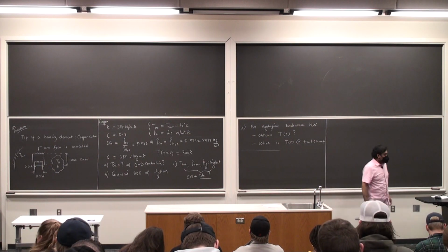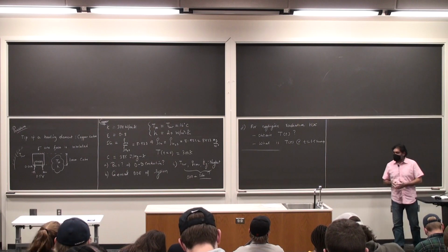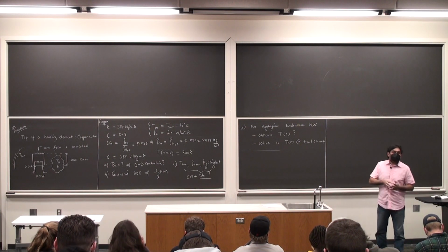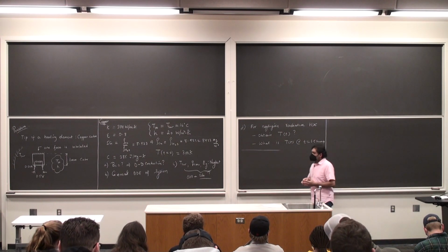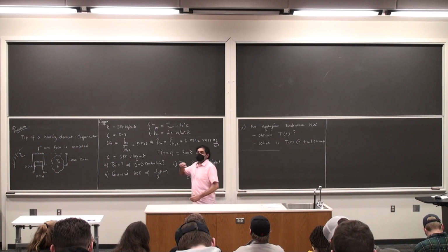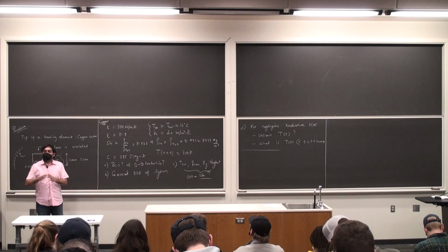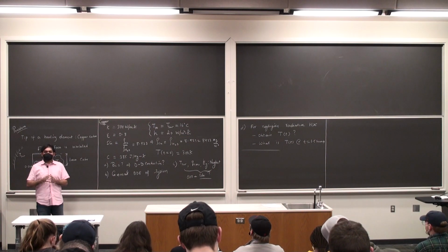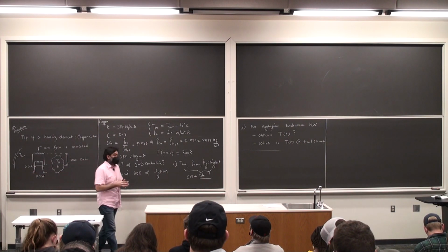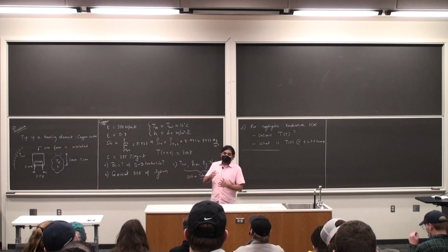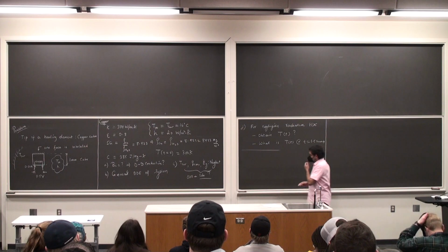So we first find out the Biot number, by making use of the typical canned formula, which we have seen in the previous lectures. When you are calculating the Biot number, keep in mind that one face of this cube is insulated, so when you are calculating the characteristic length, you have to look at the area available for heat transfer, which is sans one face of the cube. There are 6 faces for a cube, and so I'm going to consider only 5 faces for heat transfer taking place. So first step, calculate the Biot number.